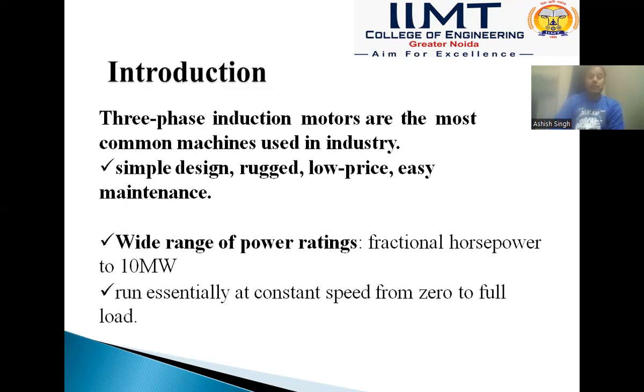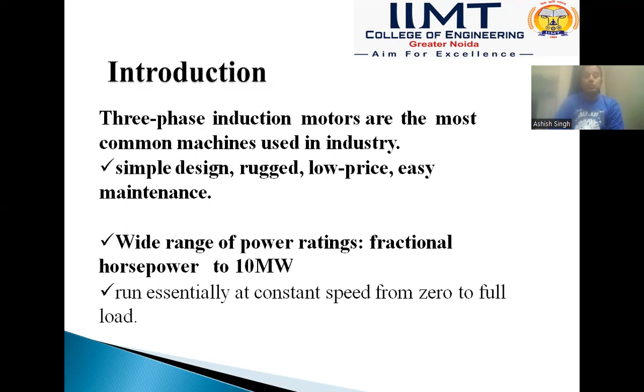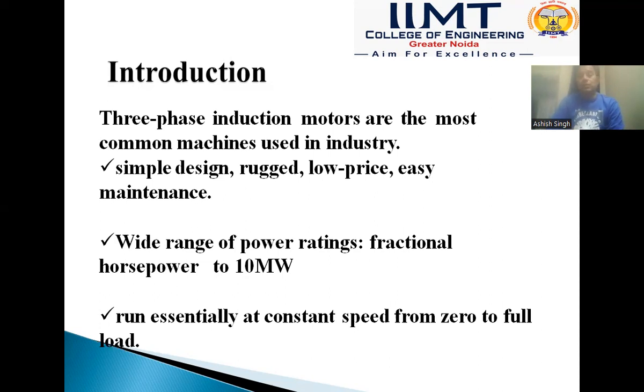The next advantage due to which it is used in industries is its wide range of power rating. It is available from fractional horsepower up to 10 megawatts of power. And next, the three-phase induction motor essentially runs at constant speed from zero to full load. This is another advantage due to which it is widely used in industries.